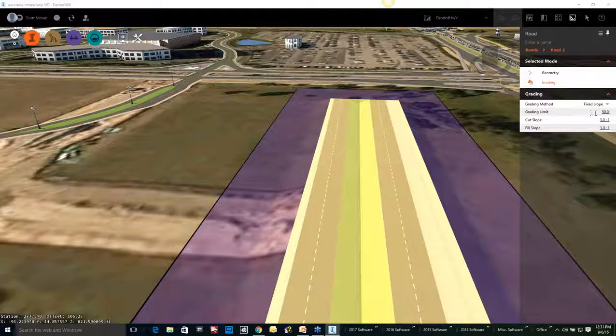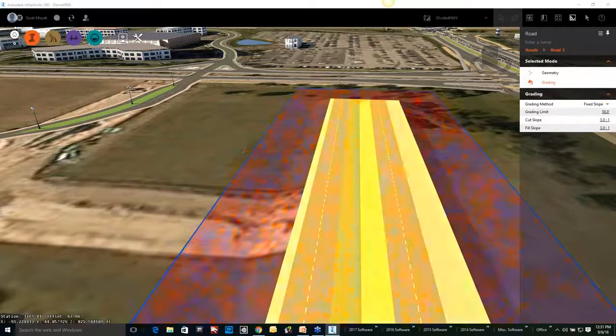And you do have the grading limit, so you can see that it'll go, I don't know, I got that go-to webinar in the way, 50 feet out, and that's my grading limit. So it will daylight within that. Now, if I went at a 3-to-1 out so far that at 50 feet I still hadn't daylighted, it will drop it off and it will have almost 1,000% slope.